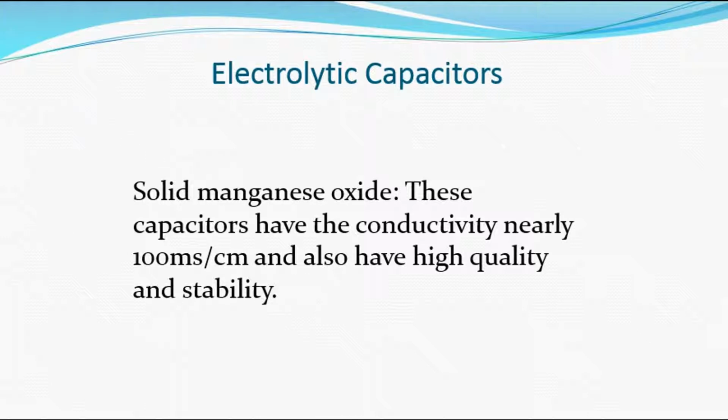Quality and stability is what you should also consider in terms of any capacitor that you are to use. Capacitor is very important. Capacitor is used even in our generator, in our lister, in so many things in our electronics. So as a technician or as a student, irrespective of where you are, if you have to substitute a capacitor, substitute the same thing that you are removing.